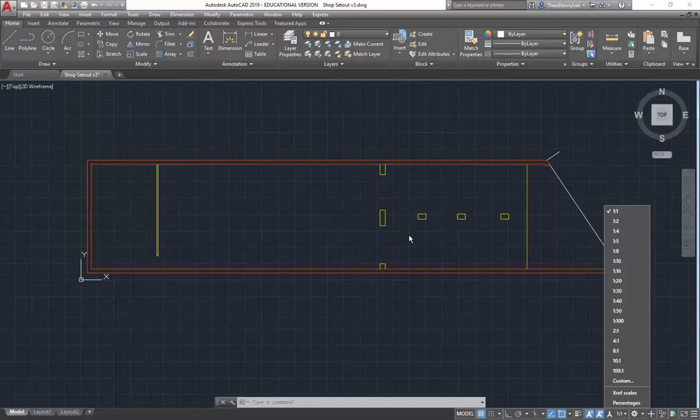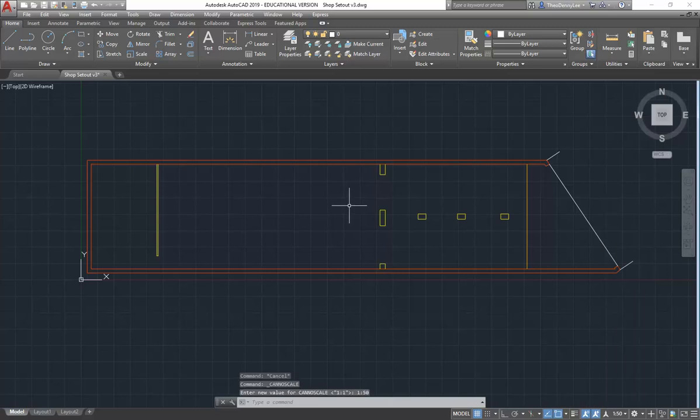So do you have an idea what scale you're going to be producing your drawings? Yeah, it should be 1 to 50, I'd say. So here, you can just click on the scale and then choose 1 to 50. We know that's our main scale. And then here you've got to remember this little command, RE for regen. Oh, regen. So it's regenerate.